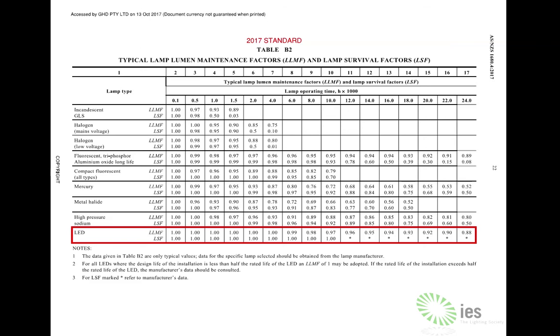Just one last comment, James. All manufacturers produce curves, but unfortunately they're curves from the chip manufacturer. Yes. And as you said before, once we put that chip inside the fitting, that's what changes. I've seen Cree chips, the curves for them, and being an electronics manufacturer, what they do is they post things as an MTBF, mean time between failure, and they post numbers that are just bizarre, like 10 million hours.